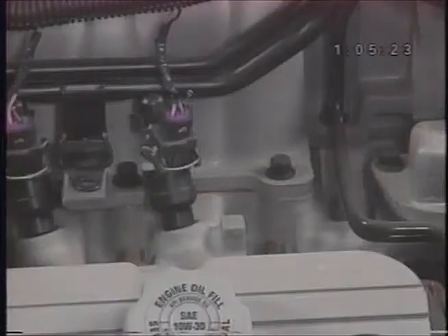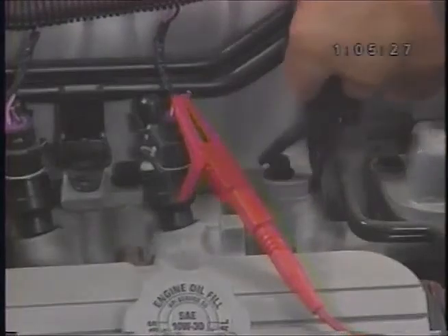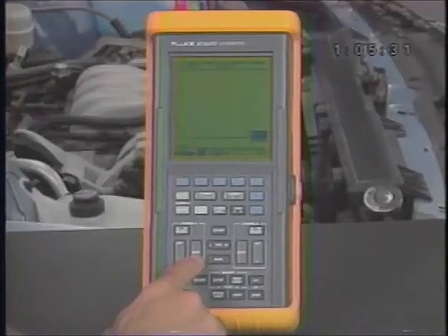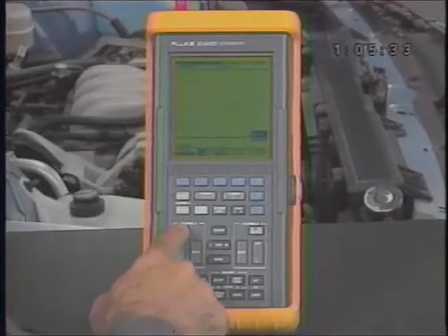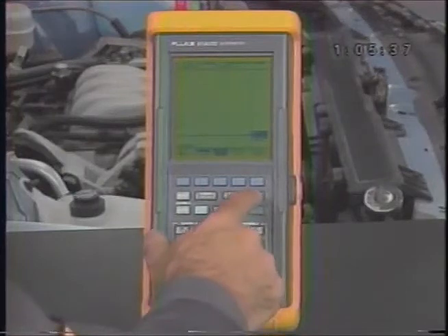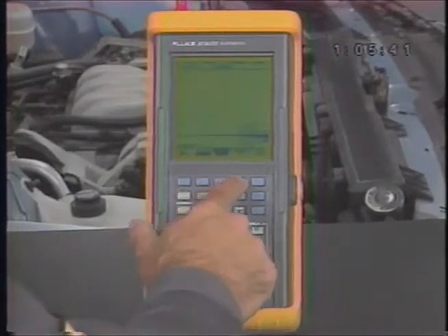By now you should be familiar with trigger delay and with using the cursors to measure time. Now you're ready to look at some real fuel injector waveforms. Connect the channel A probe to the negative side of a fuel injector and the ground lead to a good ground. Adjust the ground level to the lowest voltage division and set Scopemeter to read DC coupling. Set trigger to about 6 volts negative slope and the trigger delay to -2.